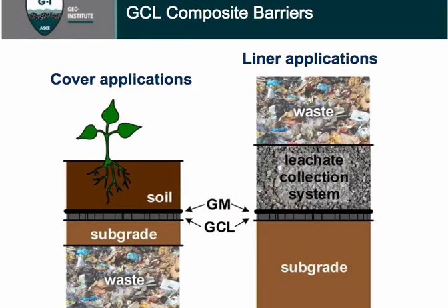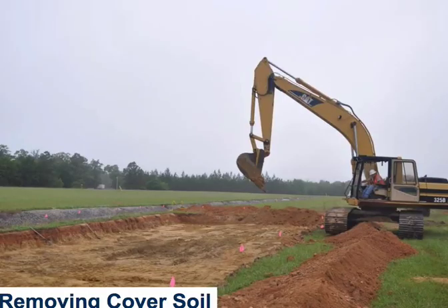So to look at how a GCL behaves in the field, you have to go out into the field. And so we've undertaken a campaign at more than 7 sites where we've gone out into the field and exhumed GCLs that have been in place for a number of years under different site conditions and looked at what is the condition of the GCL, what is the hydraulic conductivity, which ultimately is the engineering parameter we care about for the GCL.